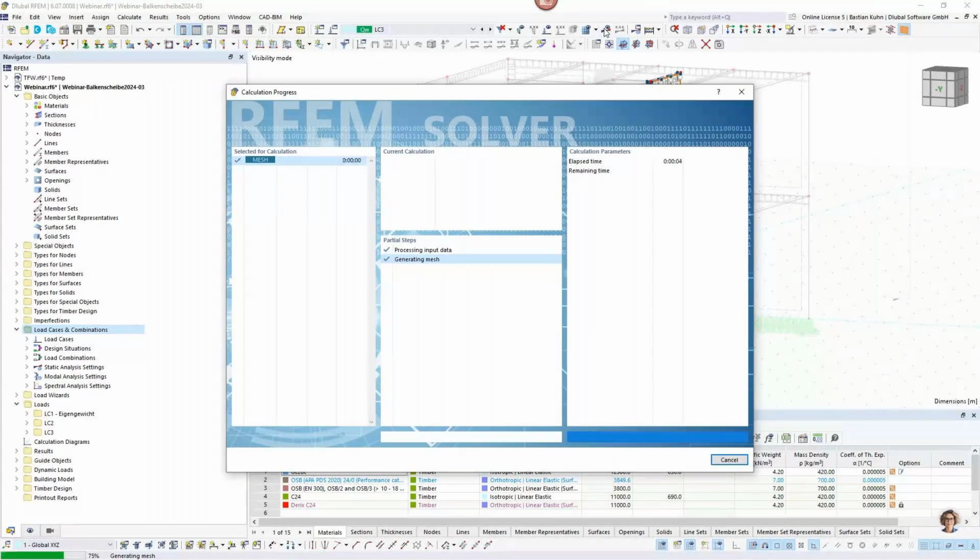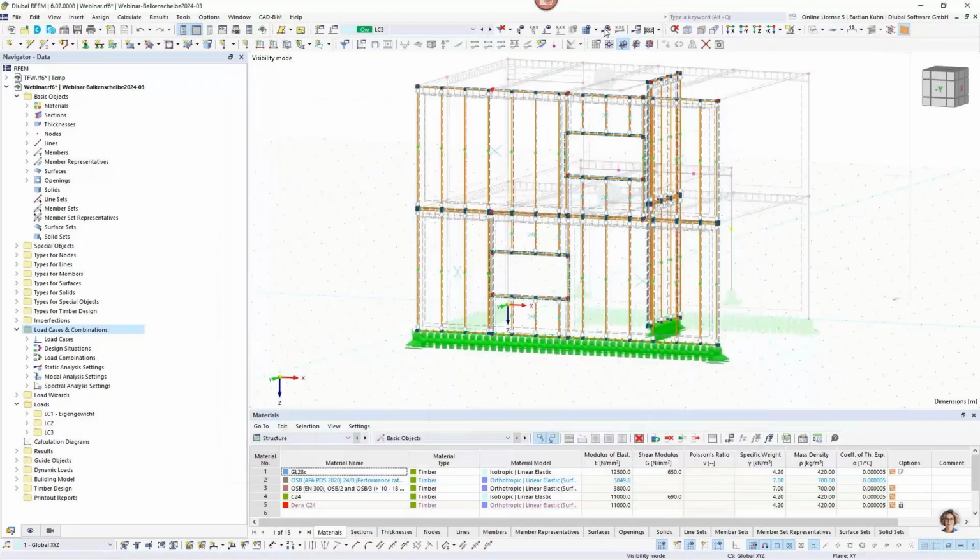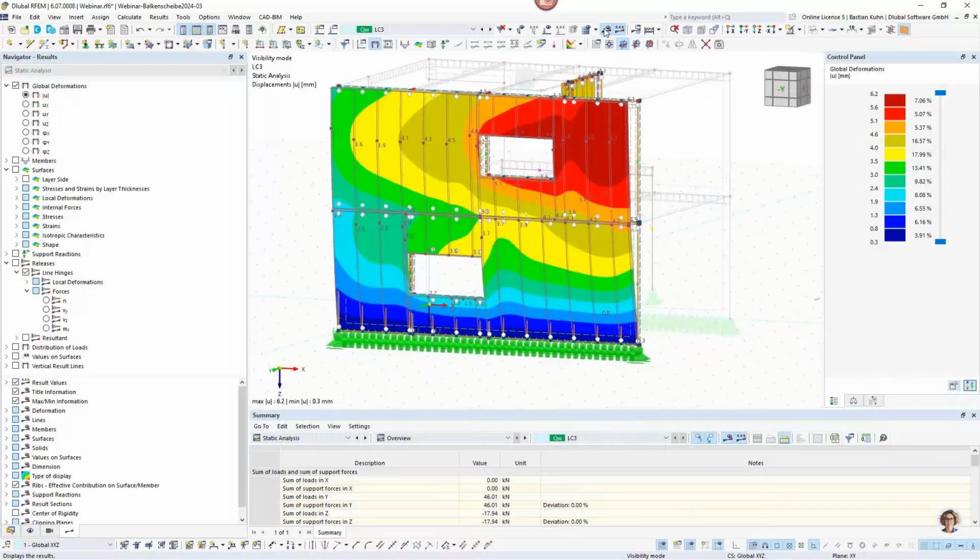Okay, it's not a real small structure, not even a big structure, but yeah. I also use the building model inside just to get my masses all around. So masses maybe also a good point. One other advantage of using such a 3D object is that you can use the stiffness of the timber frame wall similar to CLT for every calculation. So also for your dynamic analysis, you can create response vectors and use it for this.